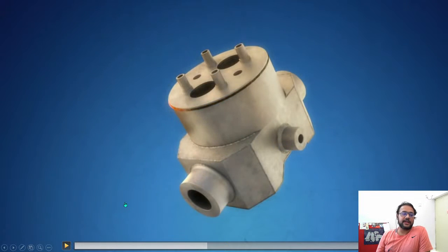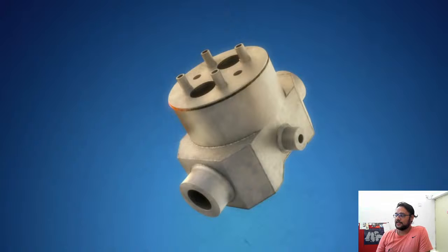Okay, so once the capsule is made, helium is passed through the whole thing to ensure that there are no leakages. Now why is helium used? Because it is an inert gas. You could use hydrogen, which is slightly smaller than helium, and it would probably give you slightly better results. But hydrogen is an explosive gas, right?